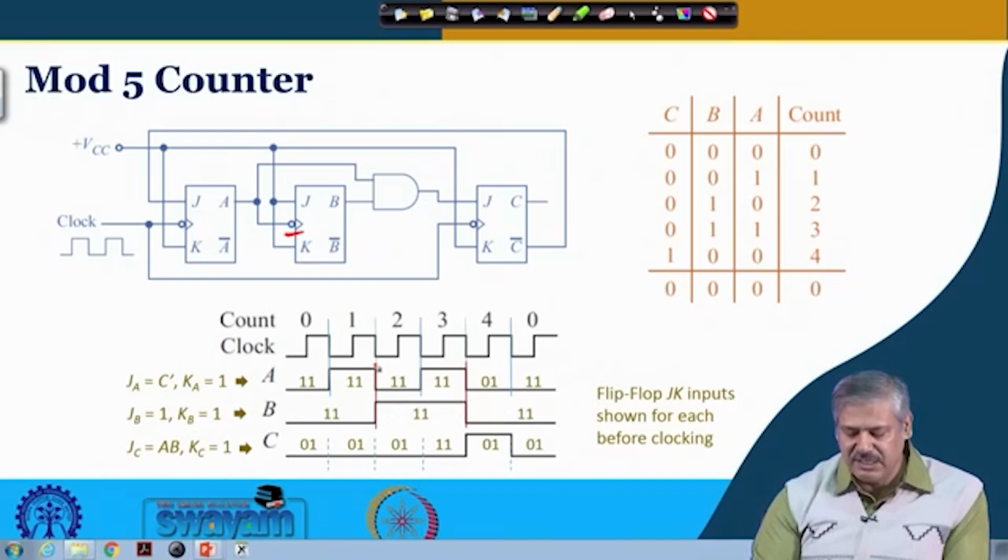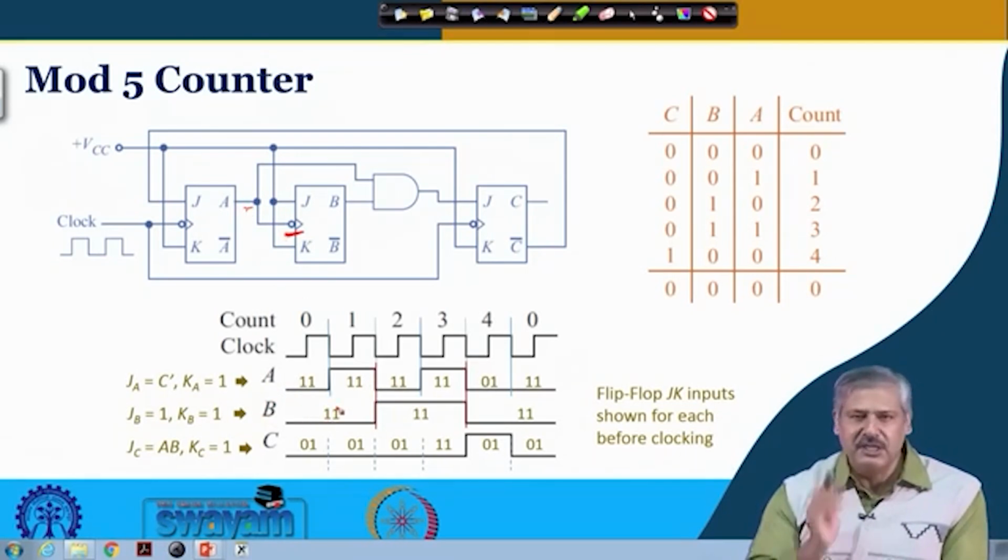B flip flop trigger is for these brown marks, okay, these brown lines that are there, which are associated with the negative edge of flip flop A output, right. So, B flip flop at that time will remain at 1 1 only, okay. Input will remain at 1 1 only and the value will remain 0, okay, for this clock cycle as well, because it has not got any clock trigger.